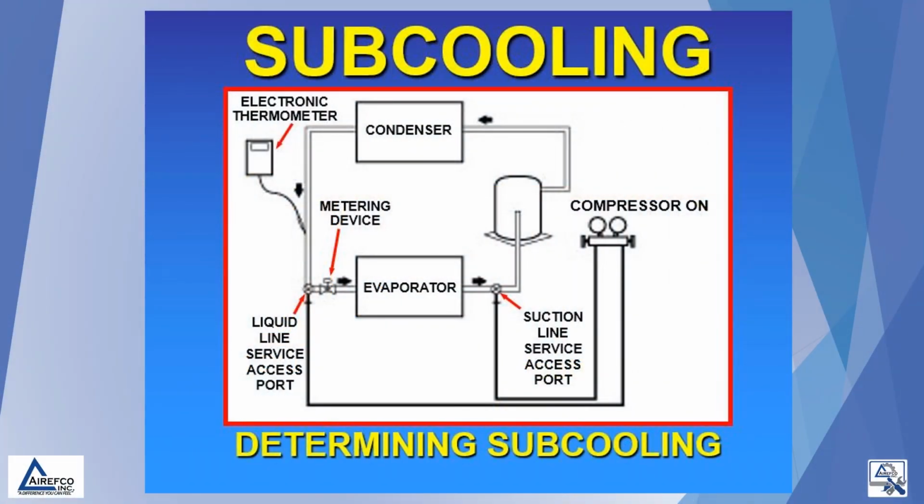In order to determine the amount of subcooling occurring in the outdoor coil, we must take a temperature reading on the liquid line of the refrigerant as it exits the outdoor coil. We also need a pressure reading from the liquid line service valve access port. We then convert the pressure reading to temperature, using our gauge or a PT chart, and the difference between the two temperatures will be our subcooling.